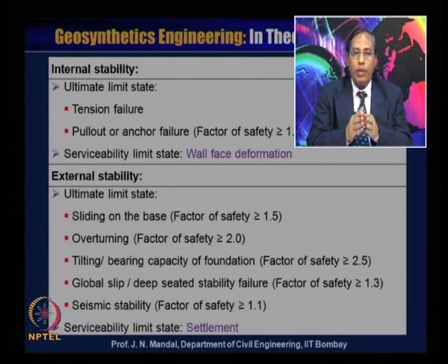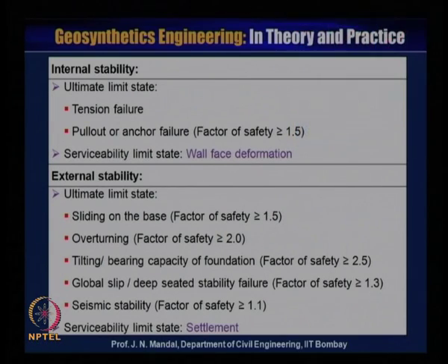For global slip or deep seated stability failure, the factor of safety should be greater than or equal to 1.3. Seismic stability you also have to check, with a factor of safety greater than or equal to 1.1. And you also have to check the serviceability limit state, that means the settlement. So, you have to check serviceability limit state for the wall face deformation and also for the settlement.